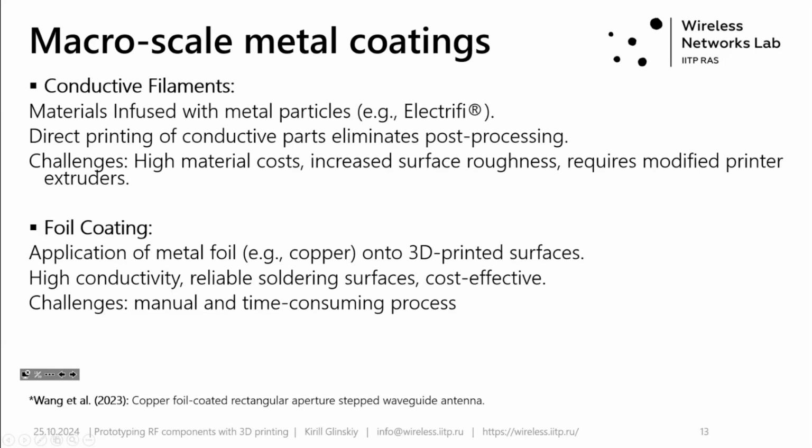As the detail is printed layer by layer, it often introduces additional roughness, and printing those materials often requires some modified extruders, so some modified nozzles for FDM printing, or modifications for inkjets, so that they can reduce the wear from metal particles.